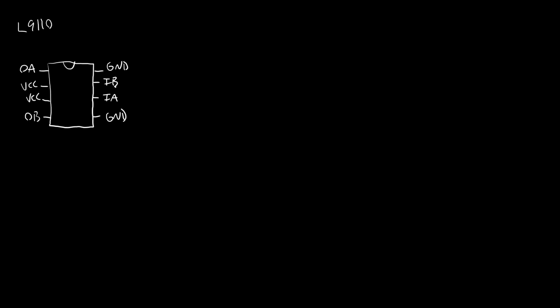And you say, okay, great, I don't know what some of those acronyms stand for. You also need to look in the datasheet for a table somewhere that explains what the different pins are. If you find that in the datasheet, you'll see that VCC is power, GND, maybe unsurprisingly, is ground. You'll note that there are 2 of each there, so even if that seems electrically redundant, that actually helps with heat dissipation. These things are designed to control higher current loads, so there's a lot of current flowing through these.